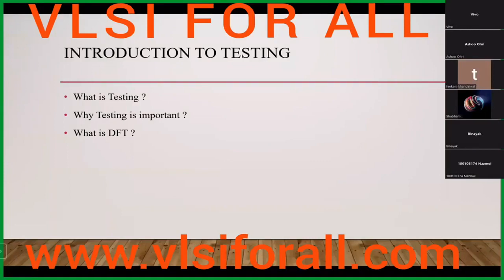Yes, sir. So what do you know about DFT? DFT is nothing but design for testability. After starting from specification to manufacture, each step of the design is verified, but it may still happen that the design can be faulty after manufacture. So DFT adds some extra logic to the design so that the design can be tested after manufacturing, in terms of increasing controllability and observability. Yes, that's actually the correct definition.